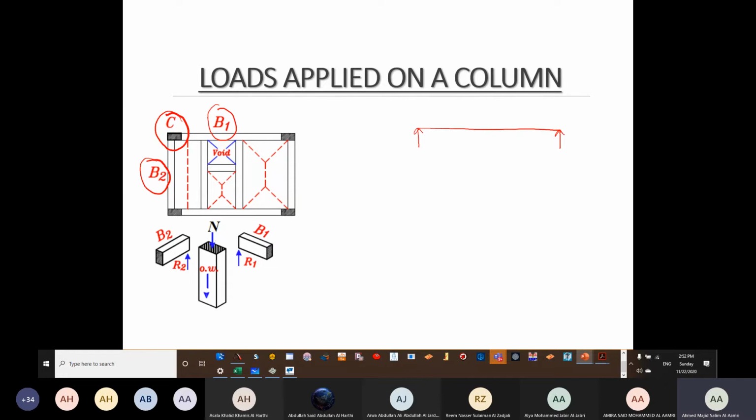And then of course there is a loading, whatever is the shape of the loading, whether it's a UDL or a trapezoidal, whatever is the shape. You will see that certain loading will go as a reaction here, and the other half is going to go here. Okay. In the other scenario as well, for beam number 2, there is a column here, there is a column here.